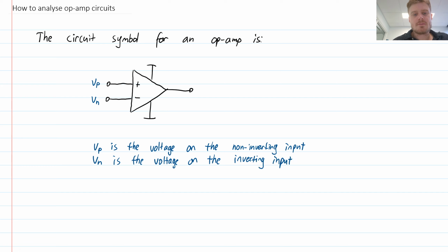Now, of course, in real life, your circuit has to have a power supply. So this is just a shorthand terminology. So you sometimes see people draw op-amps like this, and then it would be documented elsewhere what would be the actual supply rails for your circuit. If you have a design which has many op-amps, you might leave off those power supply rails because they're the same for everything. But you still need to know what they are, and you still need to connect them. It's not going to work without the power supply connected.